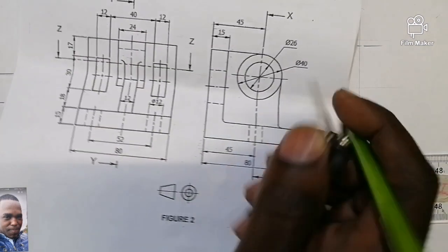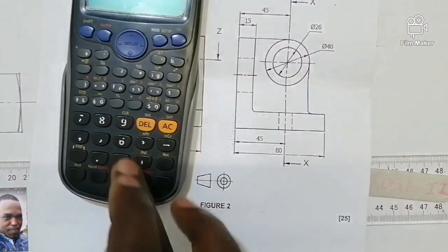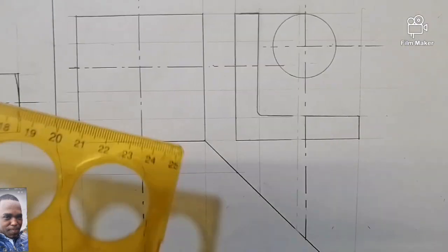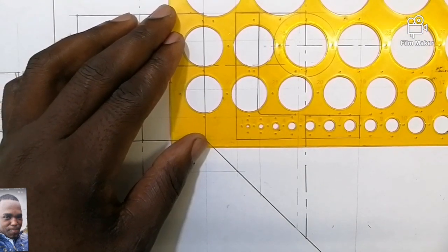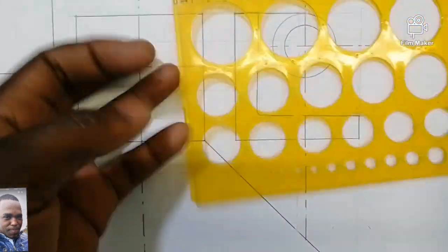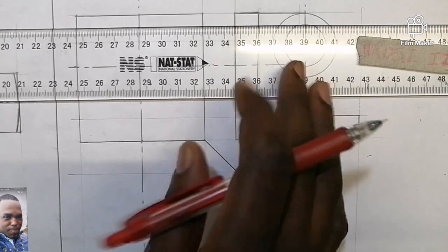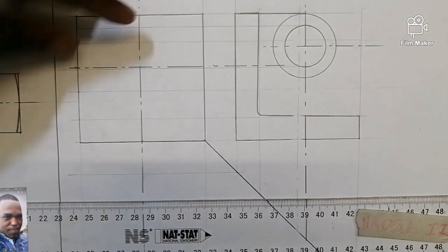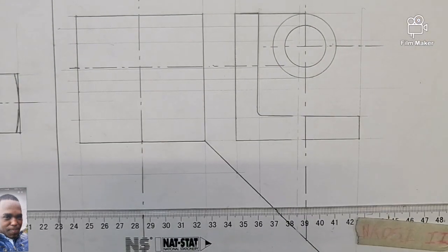Okay, so now you can draw a diameter of 26 divided by 2, supposed to be 13, isn't it? 26, 13. On the stencil ruler we do have diameter 26, which is this one. You'd be fast and accurate, like this. Then from there, project these lines to your front view, so that they will give you what seems to be missing there. Understand? So you can come back here again to draw this one.